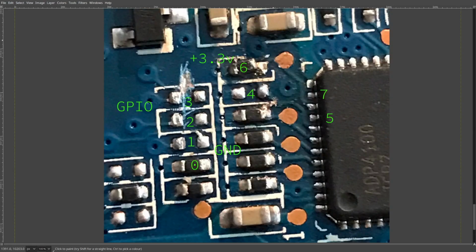So now, getting down to the actual cards that I modded. So this card, well, the only card I modded so far, is a BFG Max Core 55 that's already been kind of modded. This is an in-between state when I took this picture. And basically what you can see from here is I labeled where all the VID pins are. So you always want to connect on the right side of these resistors on this PCB. This is where VID 0 is, 1, 2, 3, 4, 6. You'll notice I skipped 5 and 7. That is because VID 5 is connected to absolutely nothing. It is a single pin here that is disconnected from everything, and as such is a giant pain to solder to. We will talk about that a bit later when I show my actual example. You can solder to it, it's just a pain.